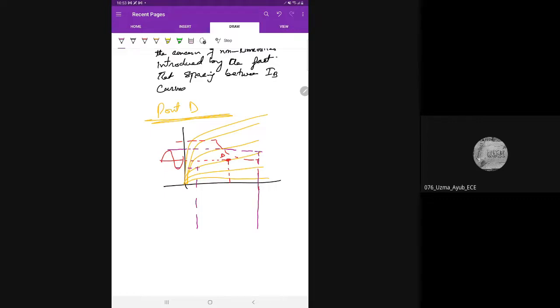अब ये जो मैं बेंडिंग कर रहा हूँ कर्व्स की, ये पर्टेनिंग टू ए पर्टिकुलर कर्व कर रहा हूँ। अगर आप देखेंगे पर्टेनिंग टू ए पर्टिकुलर बेस करंट, किसी IB को मैं ले रहा हूँ कांस्टेंट, because IB will be always constant as far as DC biasing is concerned। फिर जो ये वेरिएशंस होंगी वो होंगी बिकॉज ऑफ AC। अब वो एक ही लाइन पे देखी जाती है किसी खास IB पे, तो मैंने ये वाला रीजन लिया है अभी। So I am trying to take this region.